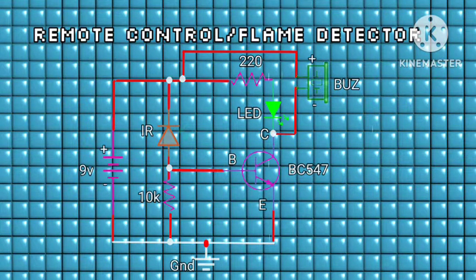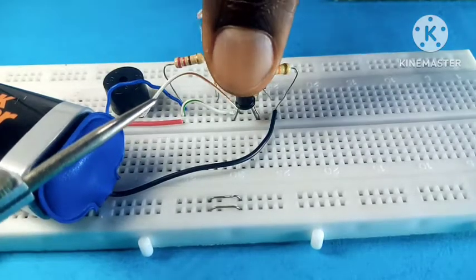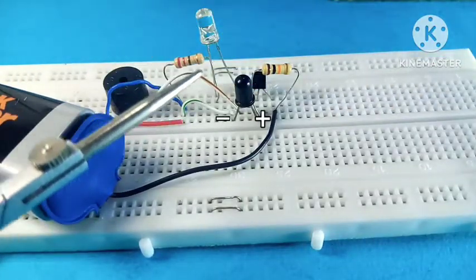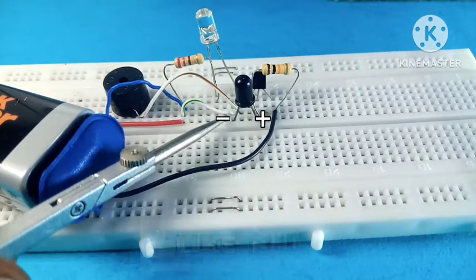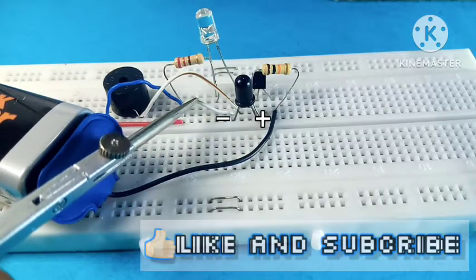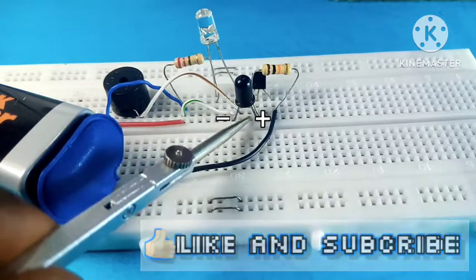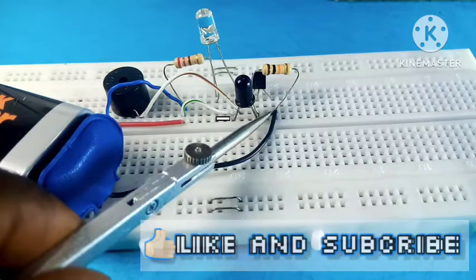Here on the schematic diagram, we can find that we have a photodiode which detects infrared, and it is used by placing it in the reverse direction, and you can see this already in the reverse position on the circuit. Here we have our circuit and the photodiode. The flat edge is how we know the cathode, and you can see it's connected to the positive side of the battery, and we have the anode in between the resistor and the base of the transistor.